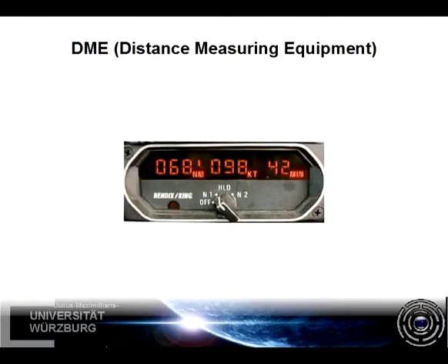This is how a basic DME receiver looks like. As you see, there is no way to set a DME frequency, only a rotary switch that allows the pilot to set the referencing navigation system, 1 or 2. Also, in case you want to change the VOR station, but at the same time keep the DME station that is currently received, it is possible to use the hold setting that is in between N1 and N2.